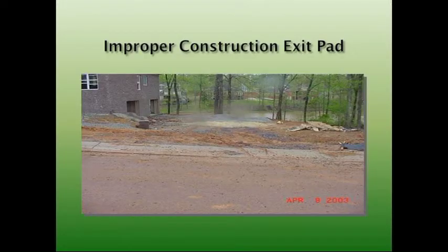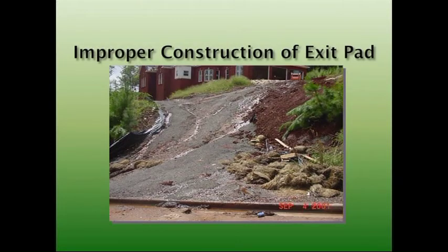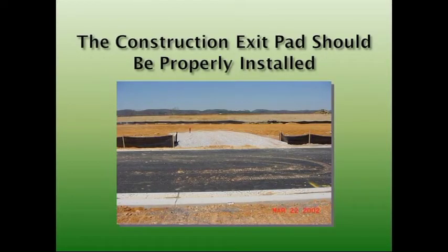You can't use that paved surface as a construction exit pad until all sediment is stabilized. So there's an improper construction pad. You see there's another one. See how there's really no sediment trap in there at all. It just becomes a nasty mess. This one's a little bit better. This one's probably a newer developed subdivision. There's some soil that leaves it, but not a lot. You probably want to stop it short of these drains as well, because if you put it in that drain, it's going to stop up all your water up here and probably create a mud hole and a mess right there.